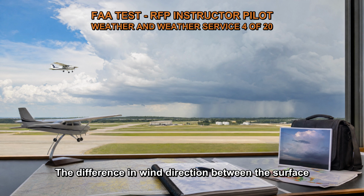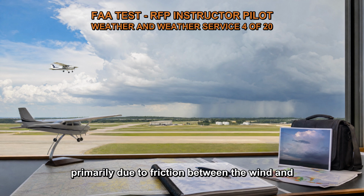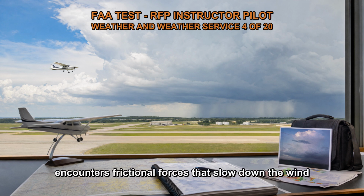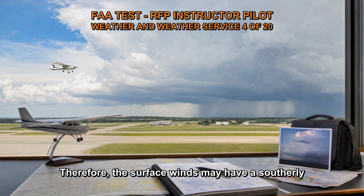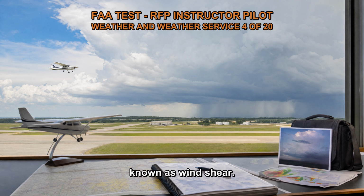The difference in wind direction between the surface and 5,000 feet AGL, above ground level, is primarily due to friction between the wind and the surface. As air moves across the Earth's surface, it encounters frictional forces that slow down the wind near the surface. This frictional effect causes the surface winds to have a different direction compared to the winds at higher altitudes. Therefore, the surface winds may have a southerly direction while the winds at 5,000 feet AGL may have a southwesterly direction. This difference in wind direction with height is known as wind shear.